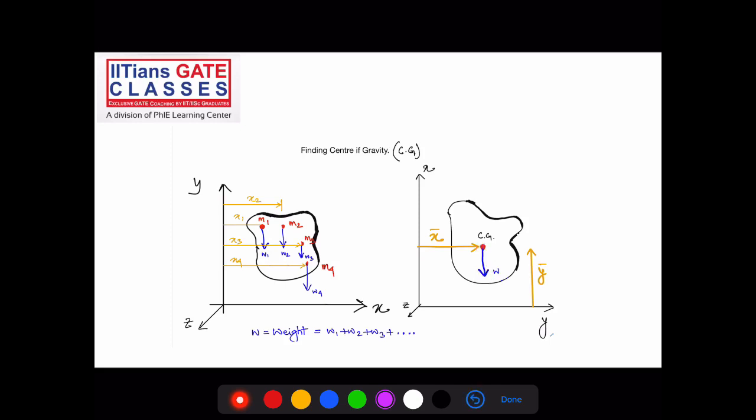So we should be able to use either of these. If these two systems are equivalent, then we should be able to use either of them, right? Here I have neglected the z direction. I have assumed the thickness to be very small and constant throughout, and I am deriving the coordinates of center of gravity only in x direction and y direction. I am neglecting z direction.